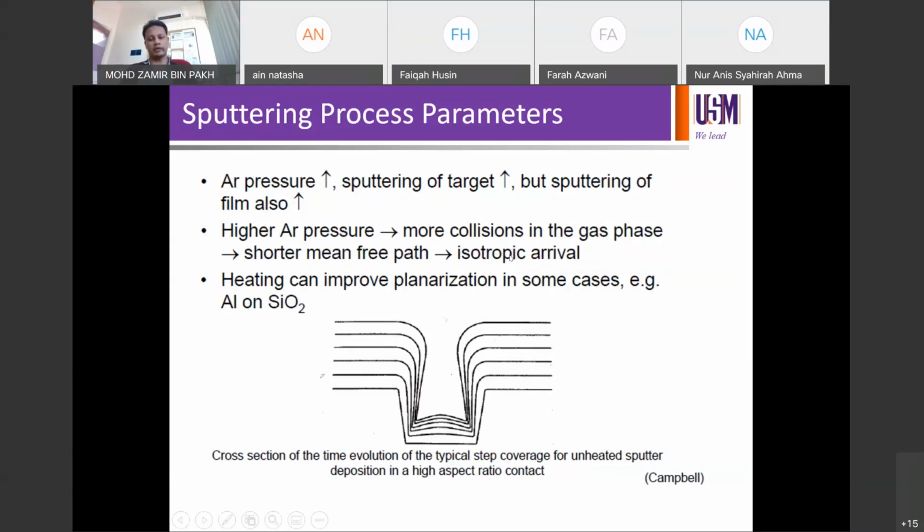You can also vary things. You can change the argon pressure to be able to change the deposition process. You can, in fact, use higher pressure. For example, if you do your process at 5 millitorr, we first pump down to a base pressure of about 10^-5, then you inject the argon, so you increase the pressure to about 10^-3. So this is like 5 times 10^-3. You can, in fact, vary the amount of pressure, 5 millitorr or 7 or 3 or whatever millitorr, in order to change the deposition process.